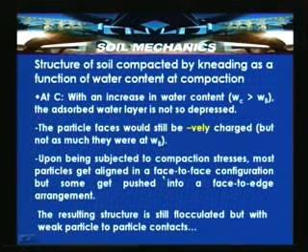So, upon being subjected to compaction stresses, since the same soil is compacted, most particles get aligned in a face to face configuration. There is now a tendency of switching particles to a face to face configuration, but some get pushed into a face to edge arrangement.